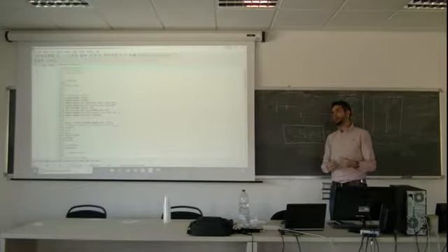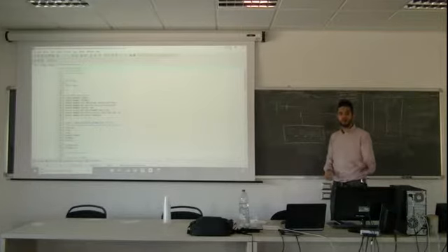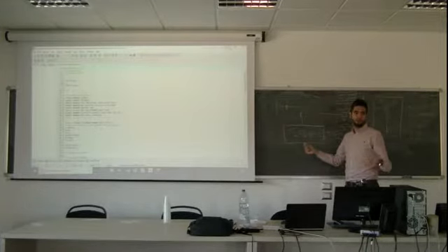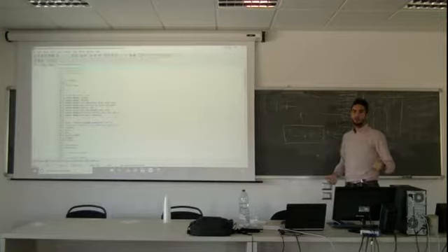So, if you relax, usually you will need more iterations to get the solution, but it's more probable that you get the solution. So that's why, if the problem is simple, don't relax. You can put R equal to 1, and you will go the most direct way you can.